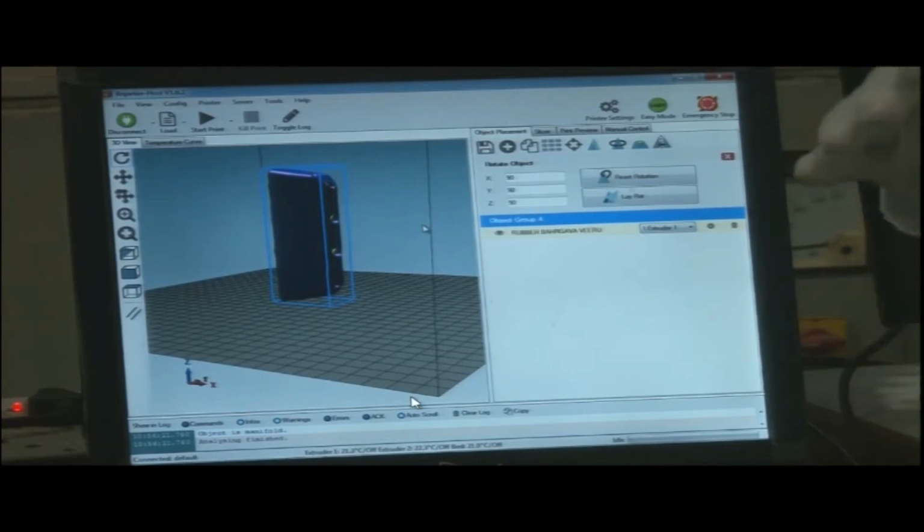What is the drawback when we increase height? Because it is manufacturing layer by layer, this is very important to note. If we increase the height, the total time would increase. So the height has to be optimized, it has to be minimum. These many number of layers are to be deposited, so the total time would increase.